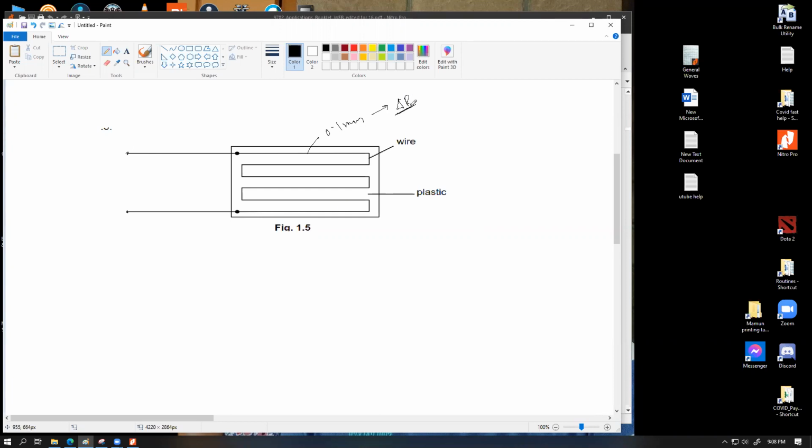Measuring this resistance is somewhat difficult compared to if you have 10 of these wires in parallel. For example, in this case, we don't have 10, we have 1, 2, 3, 4, 5, 6 of these wires. So if this whole structure extends by 0.1 millimeter because of the extension, then the total length increase for this set of wires would be 0.6 millimeter, right?